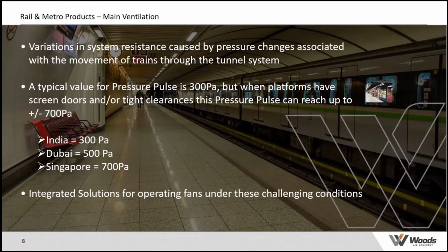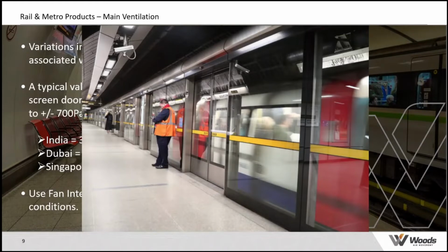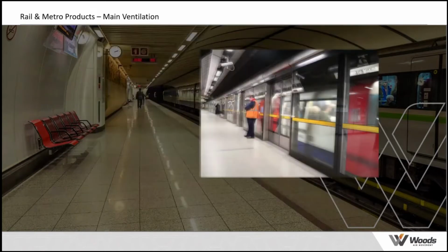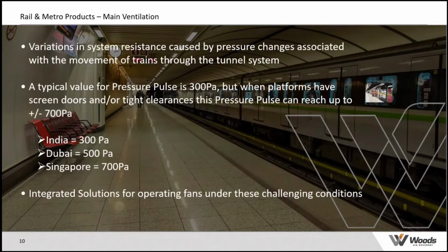Now, the picture in the background is showing a very open station, whereas in reality now, pretty much all modern metro systems incorporate a thing that's called platform screen doors. So these doors effectively separate the train from the station. Okay, and there's two main reasons for this. One, it's to help isolate the space and improve comfort. So it means you can actually air condition the station areas and the train areas, and also it's to stop anything getting onto the track, including people. So it separates people from the operational part of the train itself. So it's much improved safety underground.